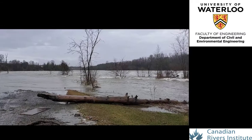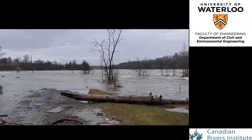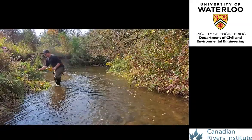The quantification of discharge, whether it be during flood flow or environmental low flow conditions, is based upon the continuity equation. Discharge, Q, is in fact calculated in rivers at any one given instance in time rather than measured. The product of field measured in-stream velocities, here identified as V, and the related flowing cross-sectional attributes, identified as A, at a given location yield a discrete discharge observation.